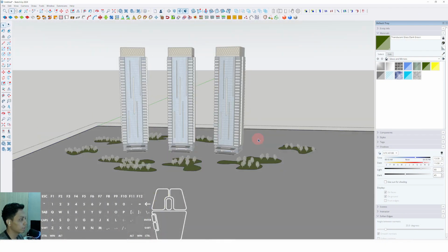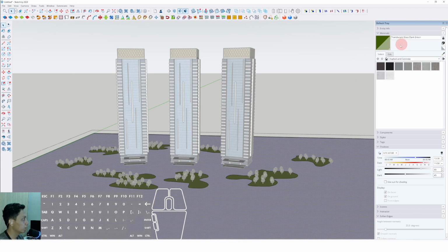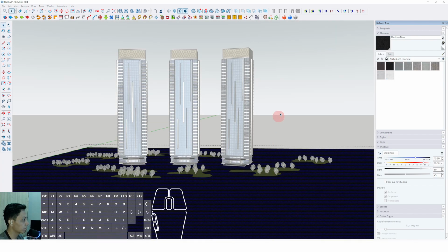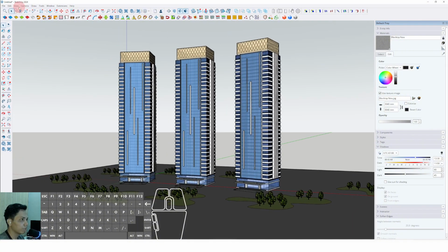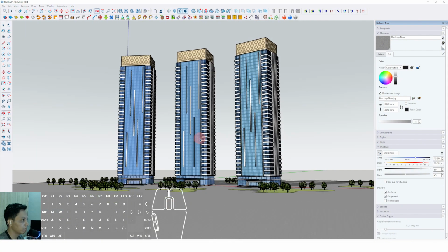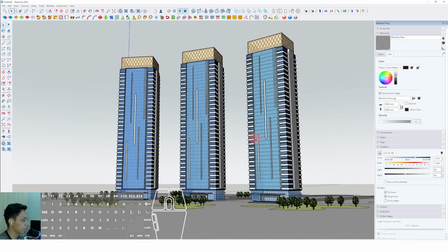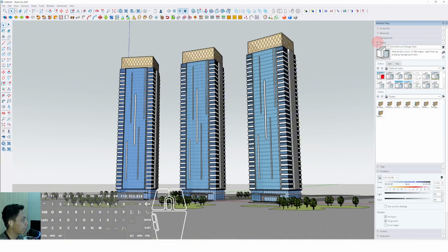Okay, so you can change the ground to be concrete or asphalt materials, and you can set the level of darkness. And now you can activate the shadow to make it more representative, and you can also change the style to the style you want.